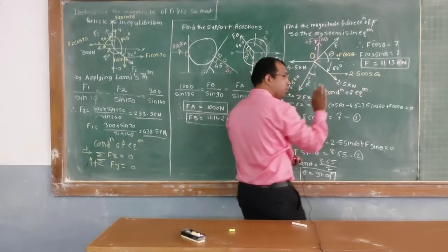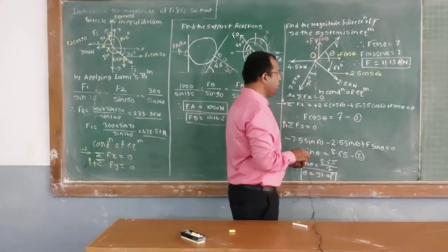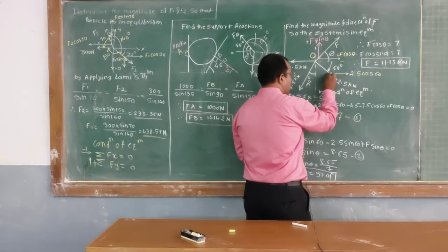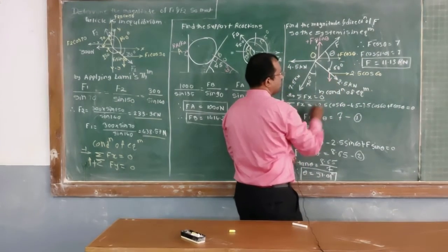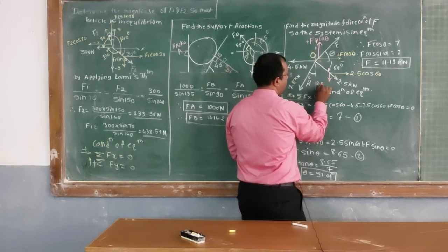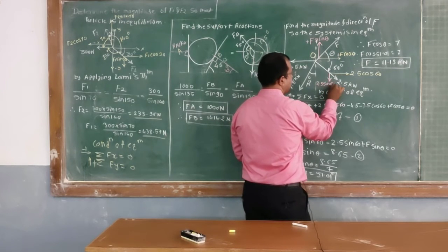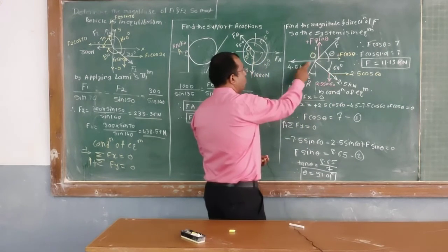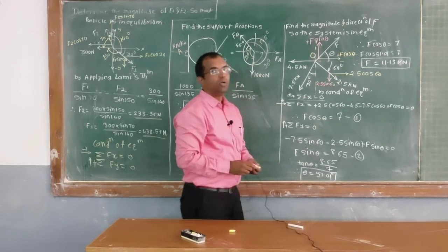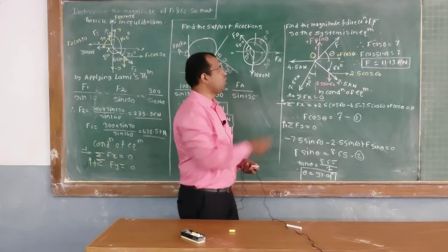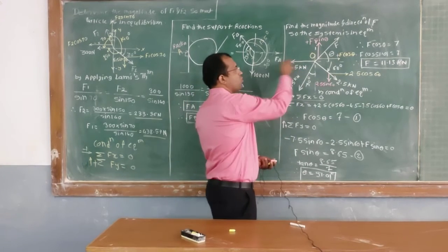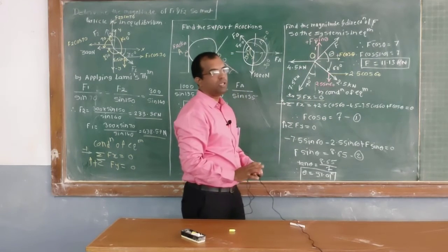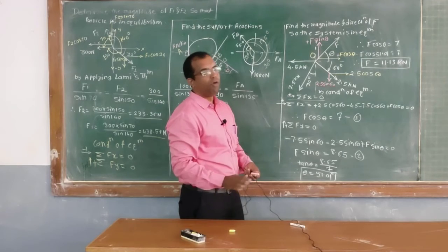There is no need to write down the sign convention. This notation just indicates that toward right is positive. Its vertical component is 2.5 sin 60 degrees. Now this force 4.5, is it needed to resolve this force? No, it is not needed because it is truly horizontal. So you have to just add this force into the Fx equation. Don't consider it in the Fy equation.